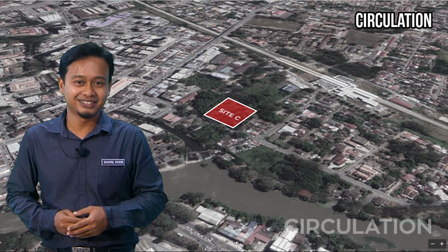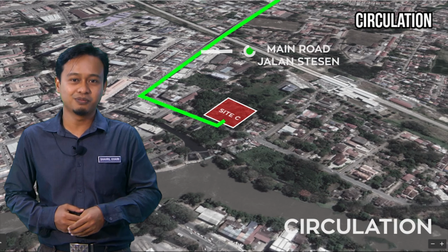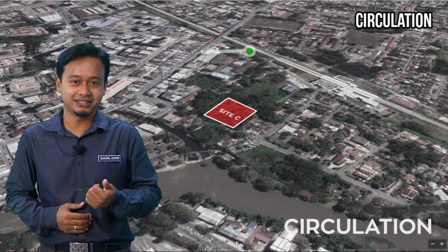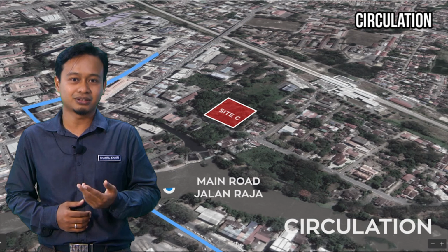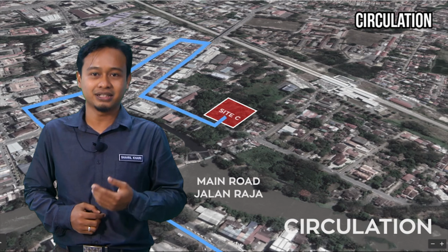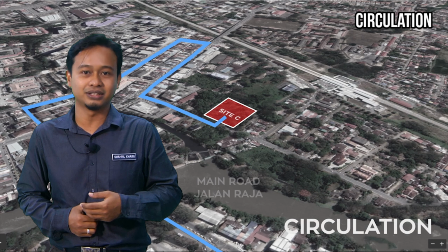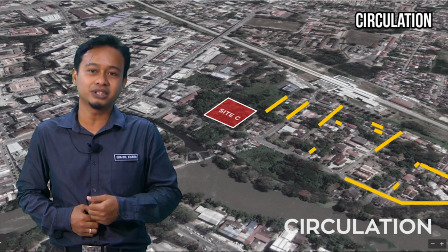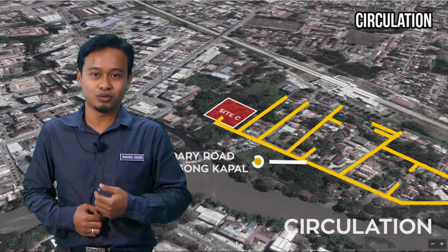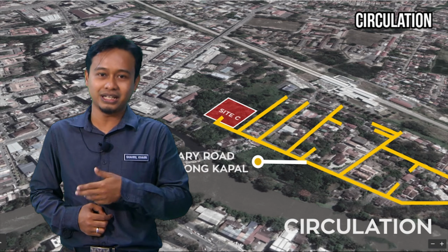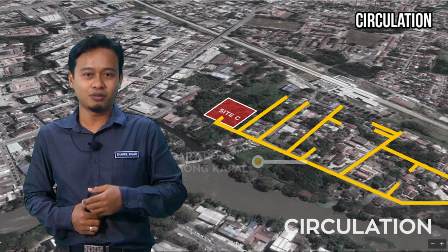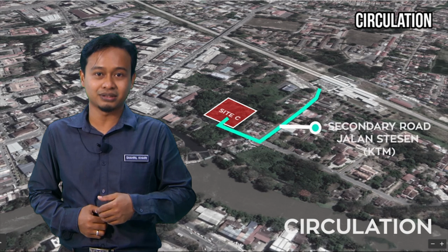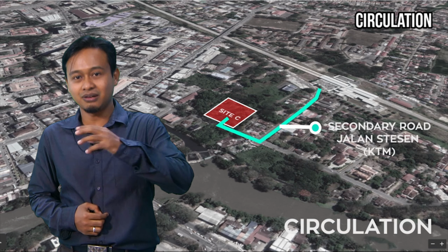Another crucial thing to obtain is the access and movement of the circulation, such as the different entry, exit, movement paths across the site and their relations or interaction with one another for people, vehicles, animals and public transport links. Most important is we need to observe the external or adjacent footpaths and informal circulation and the entry, exit or circulation paths for people or pedestrians around the site.